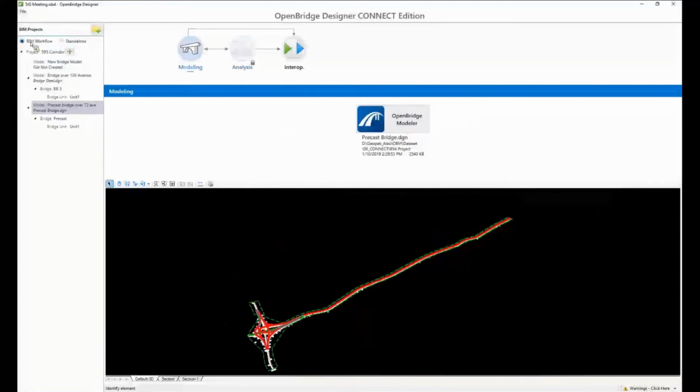If you still want to use the BIM workflow, there's a workaround with the local folders in ProjectWise that we can do offline. I mentioned it, but if it must be, you can work with the local repository files that ProjectWise creates. You can try in the meantime just working standalone, but it will be solved for sure.